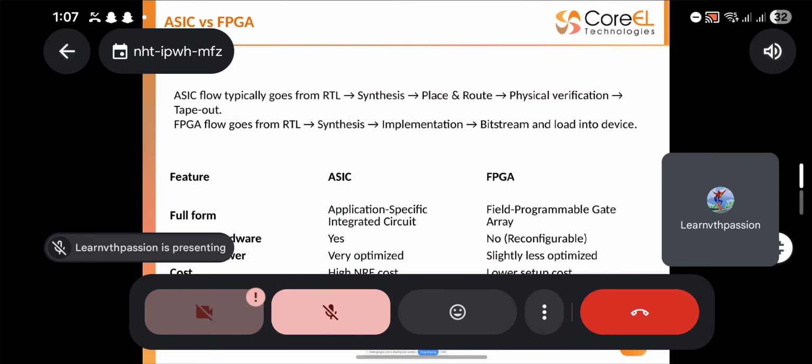But in industry, they cannot send it for bulk production without verifying the multiple things, the process which they have to carry out. So they will generate a SPICE file using PEX, and take that into the post-layout simulation. Again, they will go to the Tanner EDA, and there they will perform the post-layout simulation. They will add that SPICE file, and again they will rerun the simulation. That is how the post-layout simulation will work. Similarly, we will have the RVE directory also. That's the result viewing environment where the results will be found. So this is about the complete verification part.